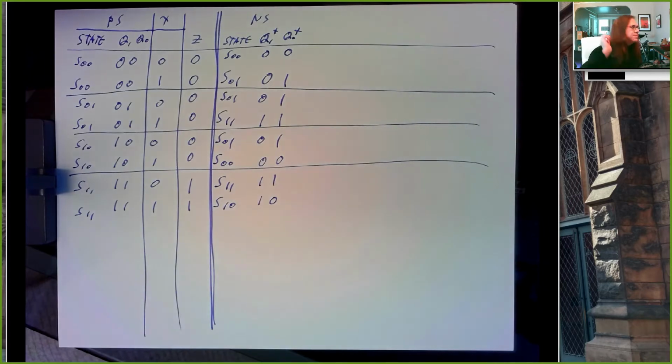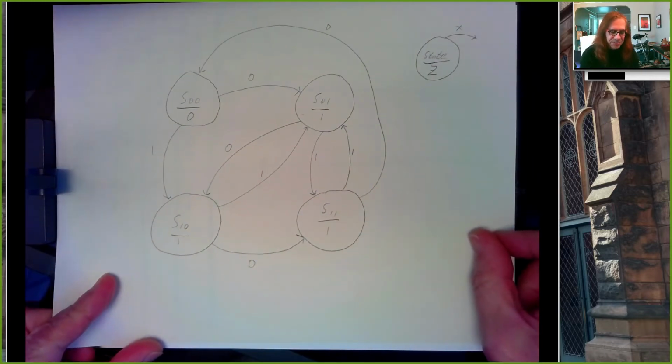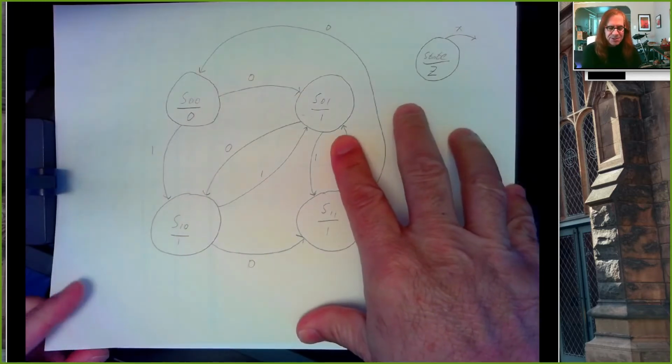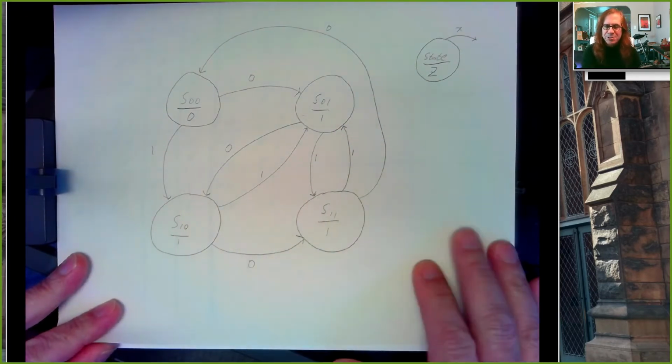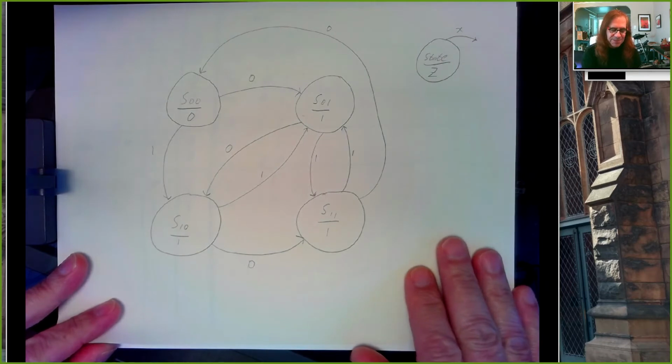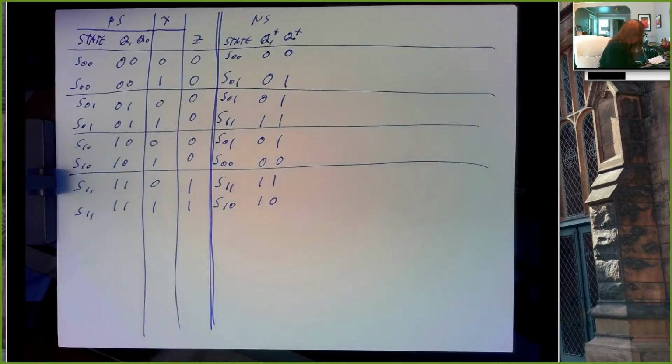I haven't checked the homework yet, but basically we start from the bubble diagram, right? Correct, the state diagram, and then we work our way after this. Okay. Yeah, so the homework I think was this, and it's 3 questions. Build a machine for this using D flip-flops, build a machine using T flip-flops, build a machine using JK flip-flops. So the same diagram, and you just come up with 3 different implementations.